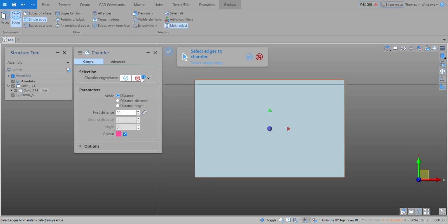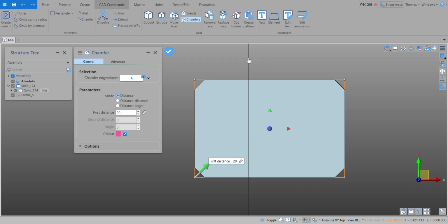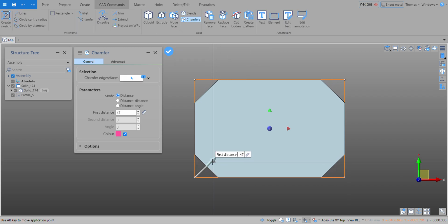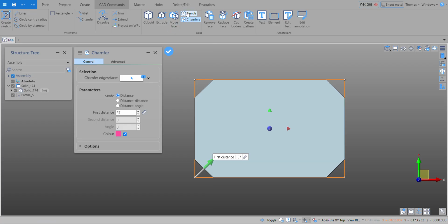See, notice here that that's increasing. I'm moving left to right so I only get the corner. Alright, and now when I go OK, I've actually got my chamfer on here. Alright, and you'll actually find this can be adjusted. Now wherever I use my blends, which is my radius or my chamfers, I can do the same thing.